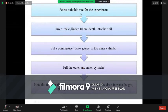In the methodology, first you have to select a suitable site for your experiment and clear the vegetation. After that, dig a 10 centimeter deep hole and insert your cylinder. For the installation, you can use a wooden plank and hammer. Then you have to insert it vertically and uniformly.